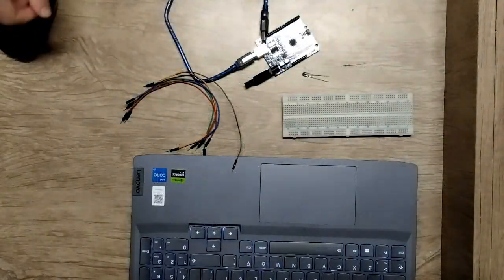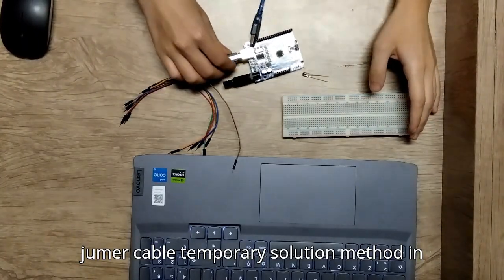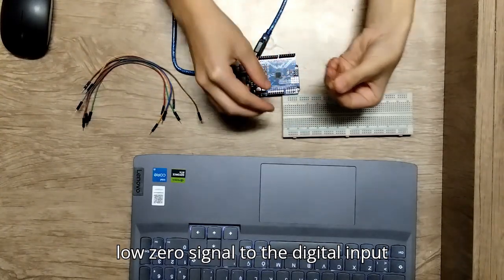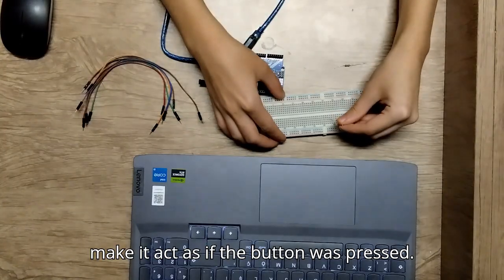Let's set up our circuit. Let's explain the manual triggering with jumper cable, a temporary solution method, in detail. With this method, we will give a low 0 signal to the digital input pins on the Arduino without a button and make it act as if the button was pressed.